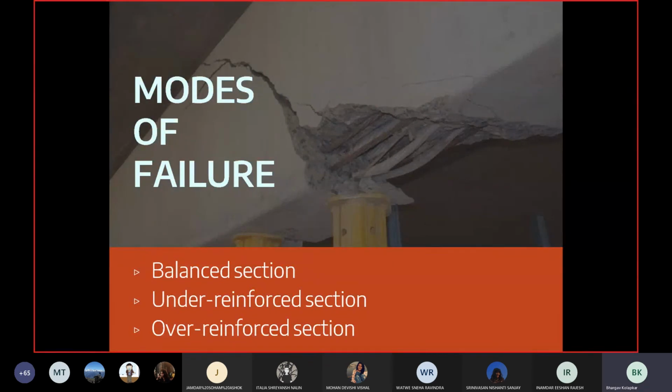So we are moving from a perfect concrete state to a concrete-only-in-compression state. In the beginning, concrete takes compression as well as tension. At the end, where the collapse is near, concrete only takes compression and steel takes the entire amount of tension.